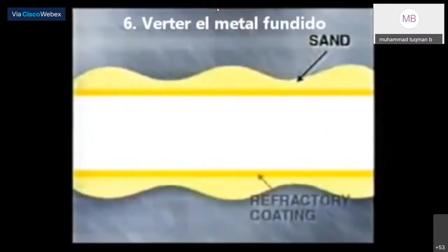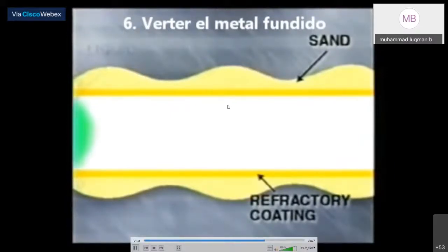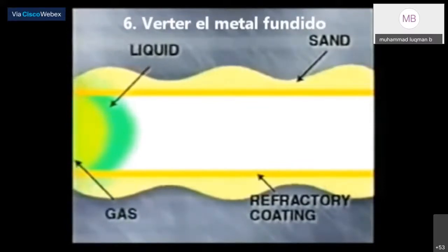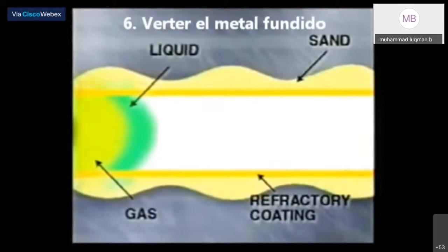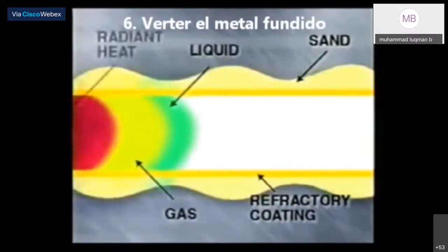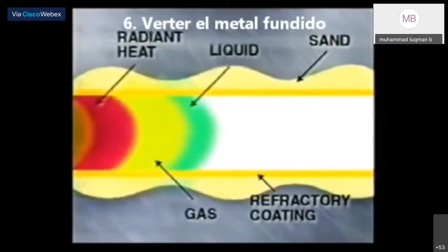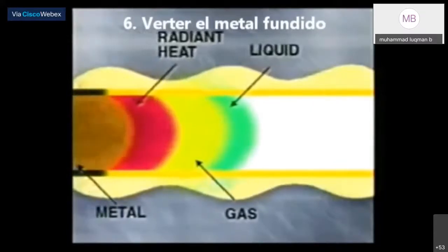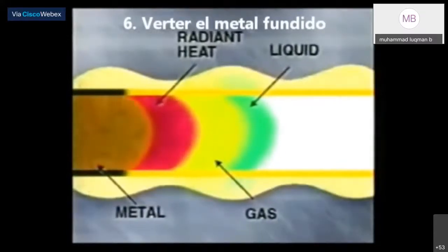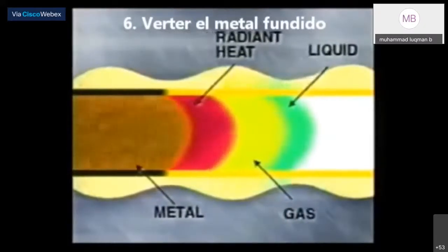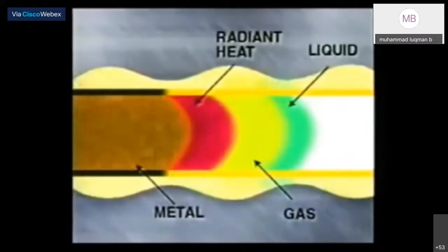As the liquid metal moves inside the coating, the heat energy causes the foam to liquefy, evaporate, and break down chemicals. The temperature of the metal poured and the foam characteristics will determine how much liquid, vapor, and gas will be formed. Special coatings have now been developed for various types of castings, which have capillary action to absorb liquids, as well as permeability to allow passage of vapors and gases. Because there is nothing in the sand to burn out, creating collapse or mold wall movement, dimensions are very accurate.